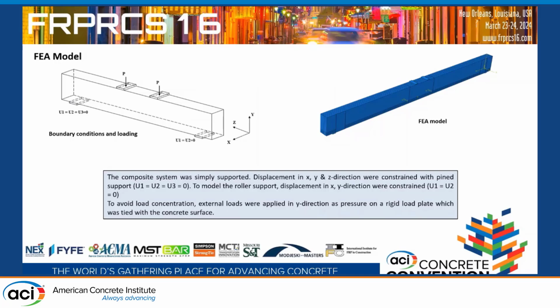And to avoid load concentration and convergence problems, the external loads were applied in the Y direction as pressure on a rigid load plate, which was tied with the concrete surface. And for the other interactions, like the steel plate at the bottom and the steel plate at the top, I used the tie interaction. For CFRP, epoxy, and the concrete, I also use the tie.